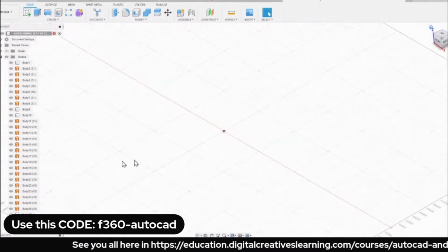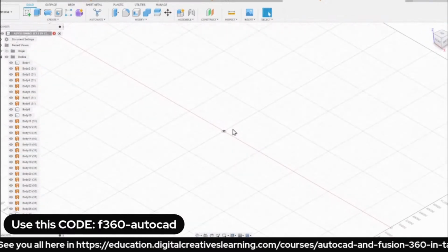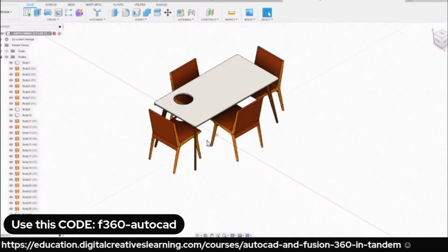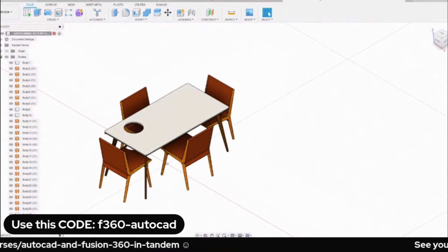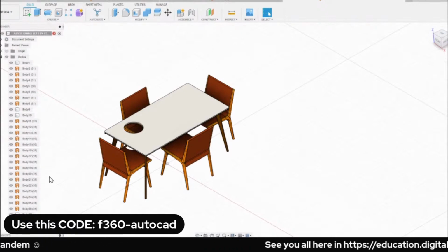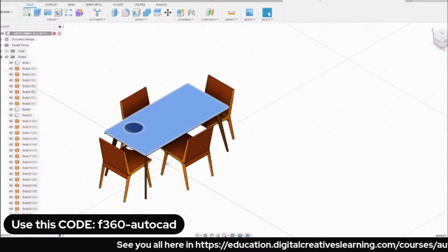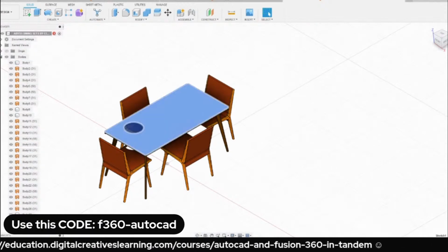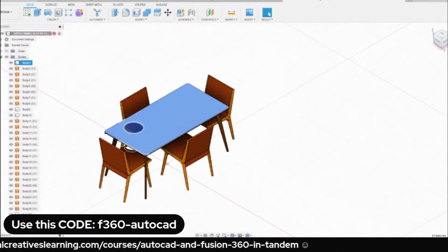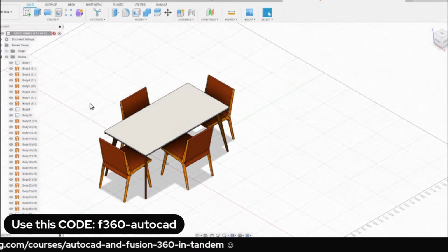And notice below, now the sketch and that extrusion command was captured. I can quickly delete or undo this command by selecting them both, holding Control and left click, hitting delete on my keyboard.